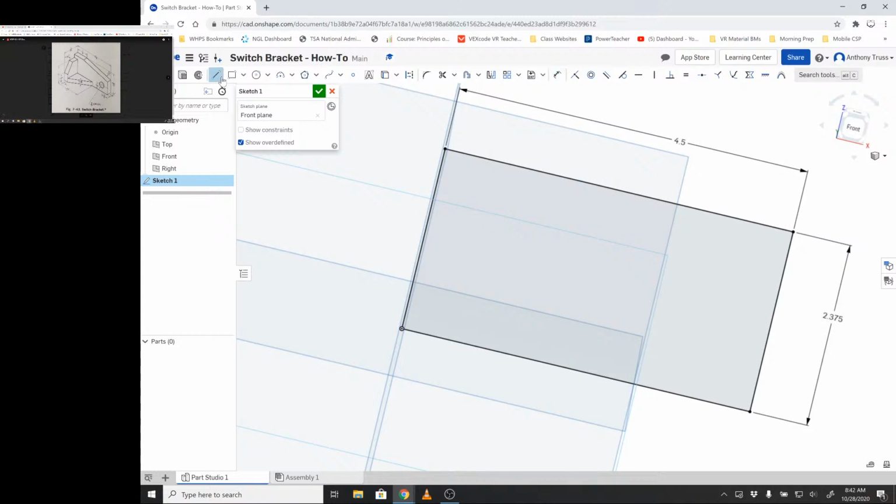With the same sketch, you're going to just use your normal straight line. Make sure your line is perfectly vertical. Even though I'm viewing in this angled perspective, I have symbols that show me that it's perpendicular and vertical. Now I've created that line, I'm going to press escape and get out of the line tool, and I'm going to right click on the line that I just created. Make sure that it's orange when you're hovering. Right click, fourth option down from the top is construction.